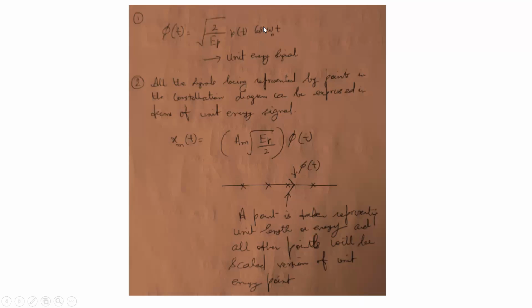Now, this is all about pulse amplitude modulation, which is a single dimension modulation technique. That means only amplitudes will be used to represent the different combinations of the bits that we need to transmit in one symbol period. So let us now come to phase shift keying.